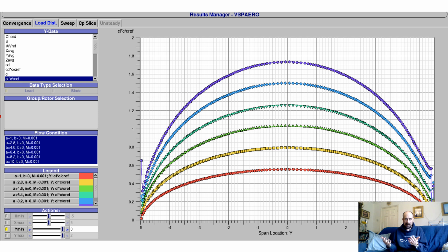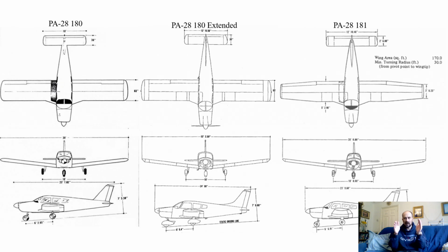So in practice, that means that on a lot of aircraft, the wing will be tapered to some extent, maybe a double taper type shape, so that it makes it a little bit closer to the elliptical shape, meaning it's easier to get the elliptical lift distribution by the twist.